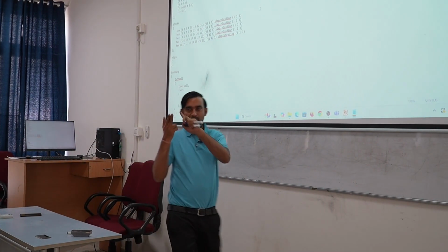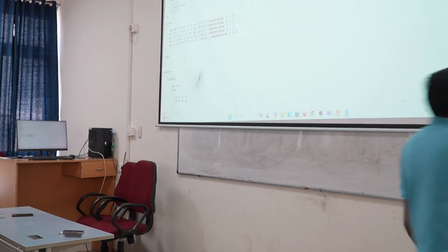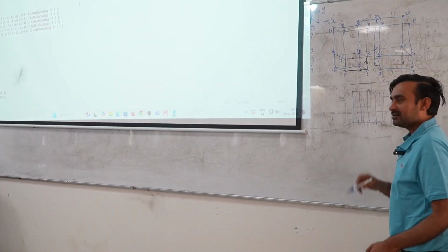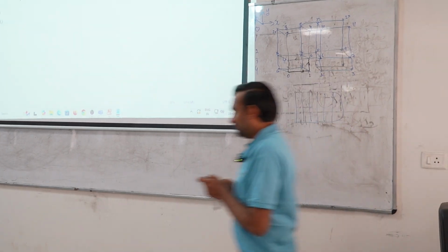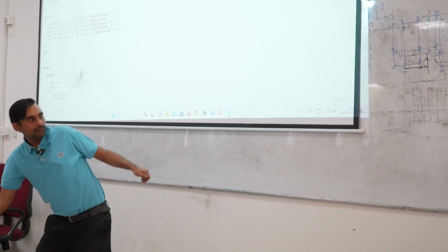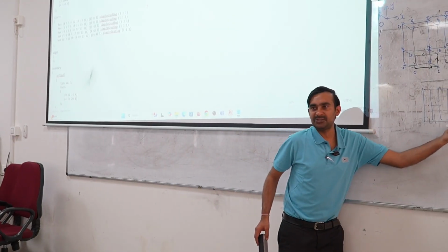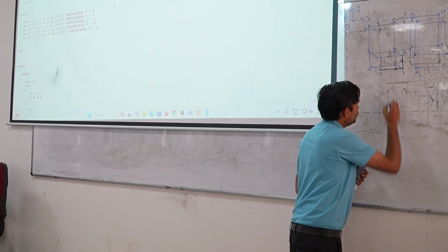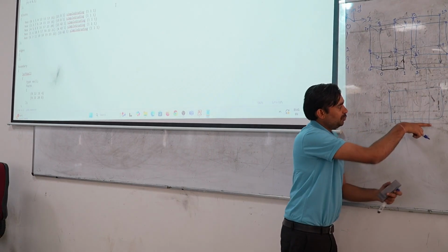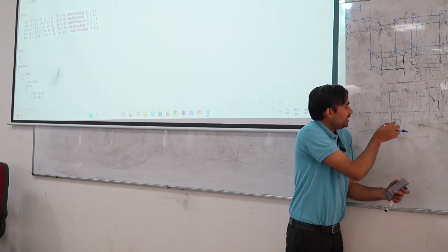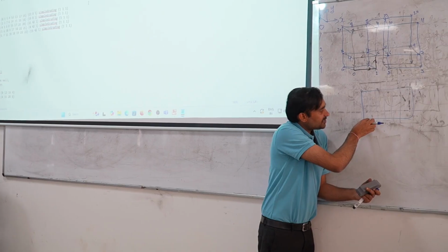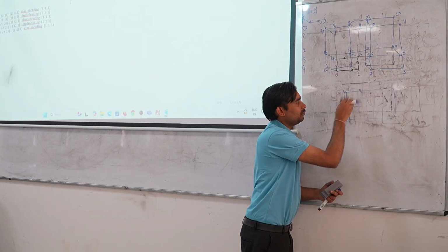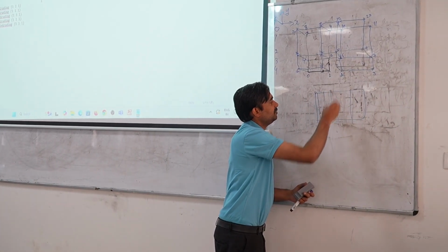Simple grading is used for 3 types of things. One is to simply define uniformly spaced number of divisions. Second is, if you want to give preference to some direction, you specify the number of divisions, along with that you also define the ratio of smallest cell to the largest cell. Accordingly it will do grading. Finest will be at one edge, largest will be at the other edge, and there will be some grading.